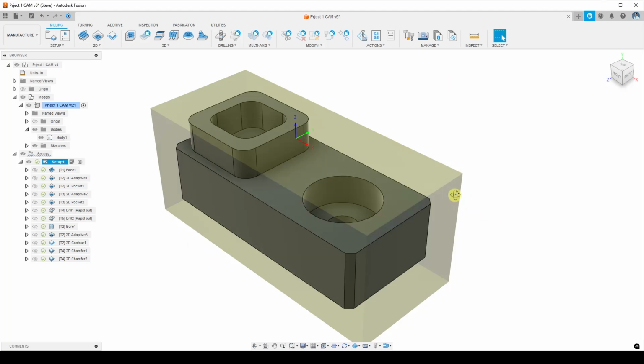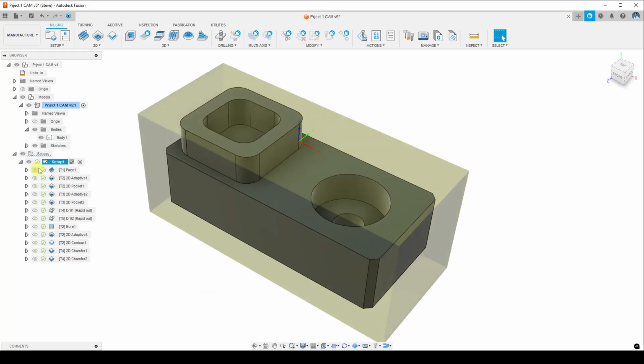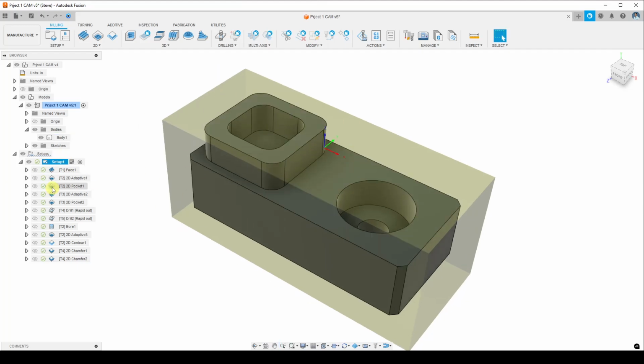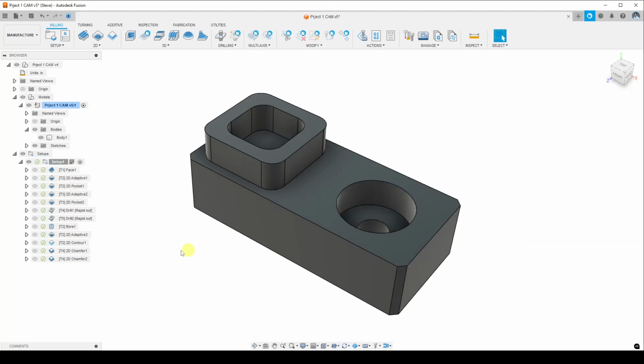The last thing that we're going to do is post-process the G-code. And what does that mean? Well, that means we are going to translate all of this information about setup and the location of the work order system with the stock and all the tool paths. Effectively, we're going to take all that information and translate it into machine-specific G-code.